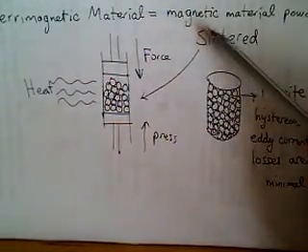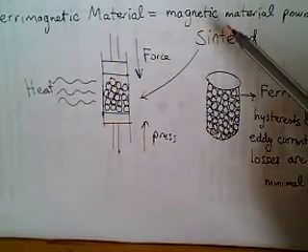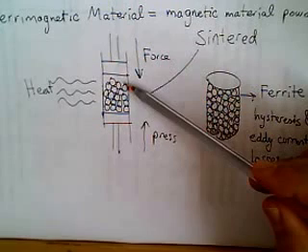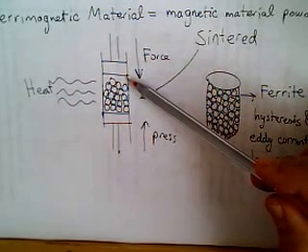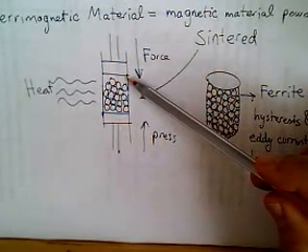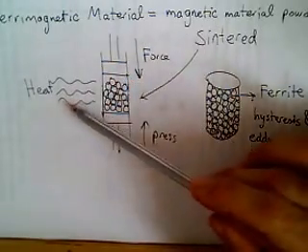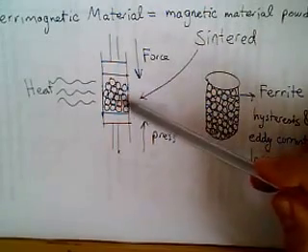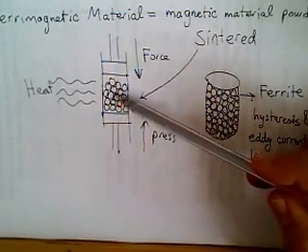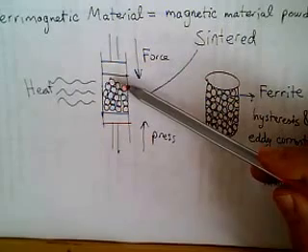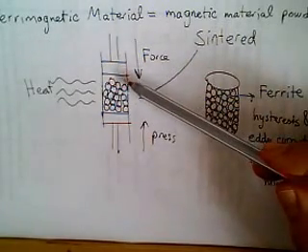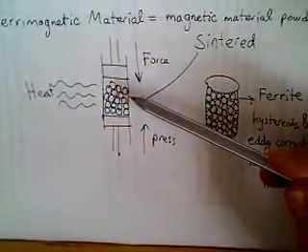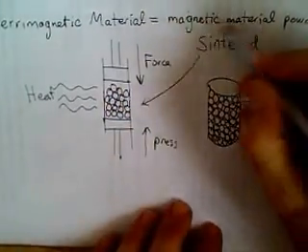First of all, magnetic material powder with very small diameter is produced, and then it is put in a strong container, which can be durable in high pressure and high temperature. Heat is applied, and by pressing, force is applied and the pressure is increased in that container, and after some time they are not quite melted, but they are softer than solid form, so they are so-called sintered.